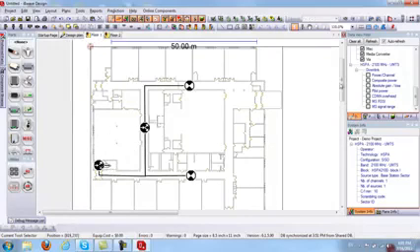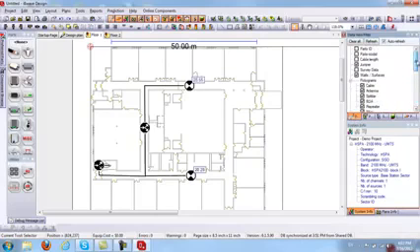So now once I'm done with the design, I can display my calculations here on my layout plan as well. I can display my power per channel at the antennas here, and I can also display my cable lengths. So here, as you see, since my floor plan is scaled, my cable lengths automatically appear here. So if I click on my antenna and move it further away, or I can move it the other direction, you see that the cable lengths are updated automatically. So everything basically is automated in iBwave design and easy to achieve.